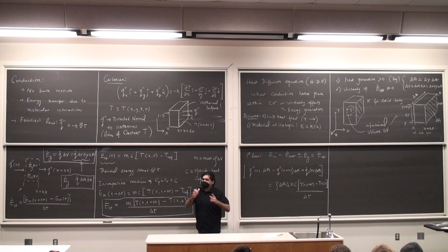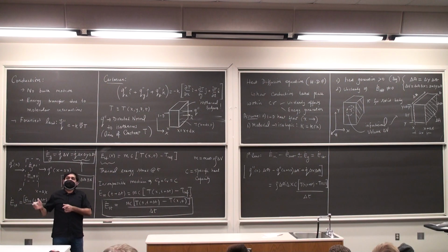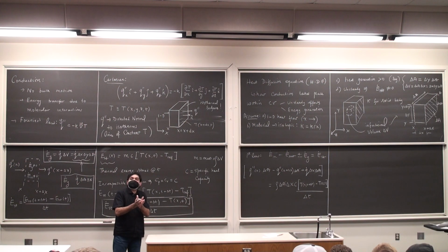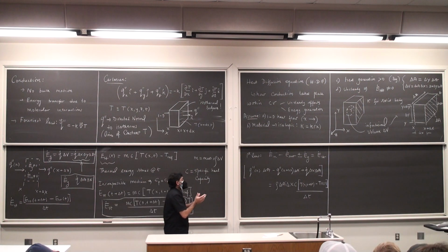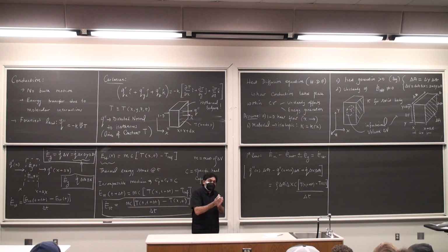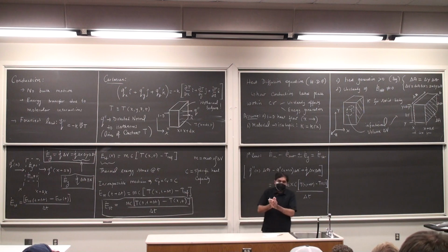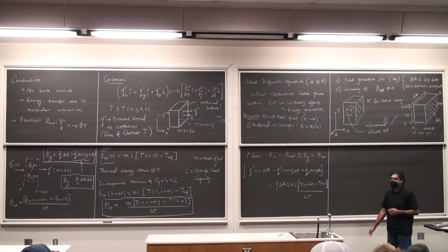And you immediately should be seeing where we are going with this. I'm going to take this delta X and spread its goodness on the left hand side. And if I then start taking limits, as delta X and delta T go to 0, I will end up with differential quantities, which tells me that this equation we are deriving is valid no matter how tiny your control volume is. So at a material point within the body, this equation is valid in some sense.